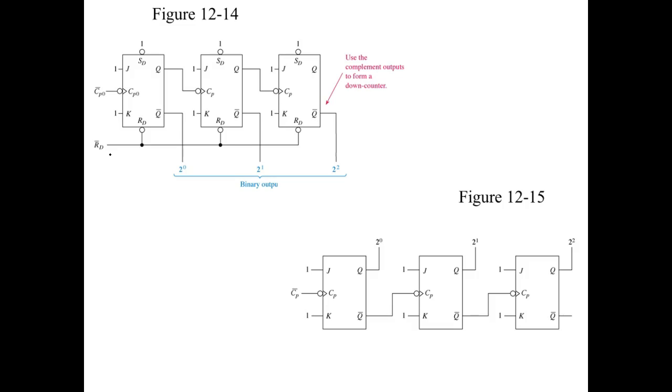These are ripple counters, and this is why they're called ripple counters, because the count has to ripple through all the JK flip-flops. These are less expensive, but how fast they count is limited, because it's set by the last flip-flop, since the count has to ripple all the way over there. If these guys don't have time to ripple all the way through, then a ripple counter can lose counts. So one of the things you'll look at on your data sheets is how fast these things can count.